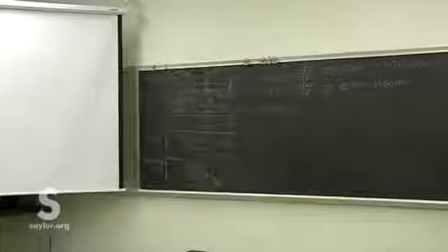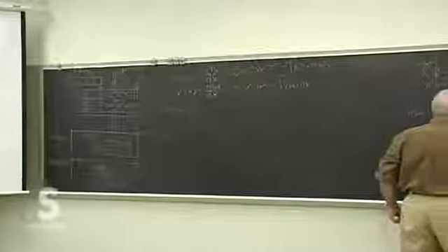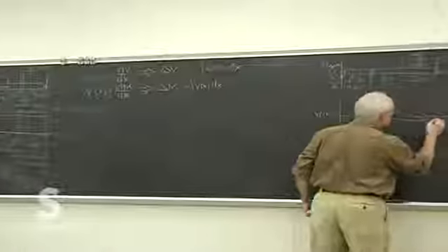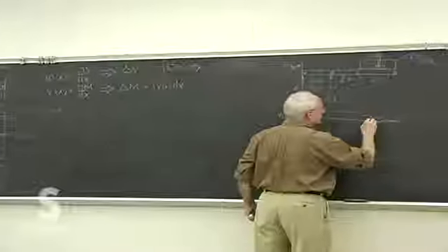All right, now we know that the slope of the shear diagram is minus the load, and we get to a free end, so we know we finish at 0. So it's a straight line coming in.